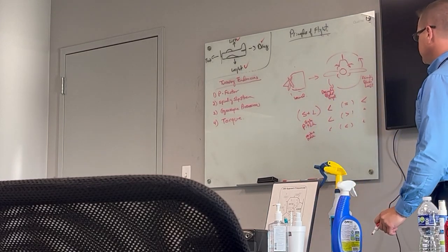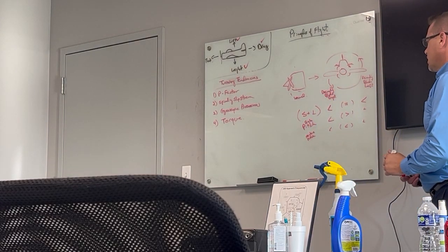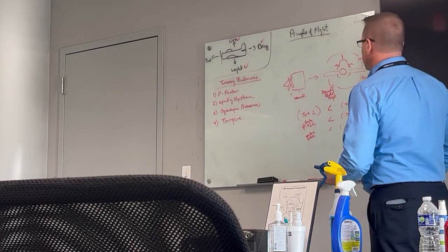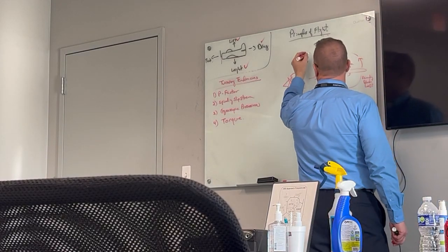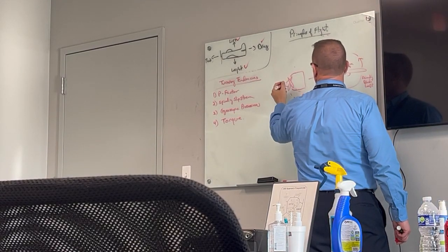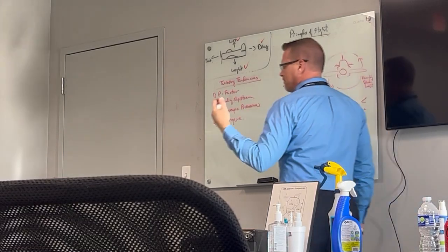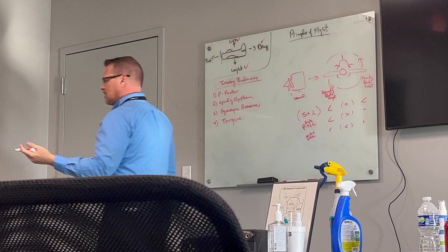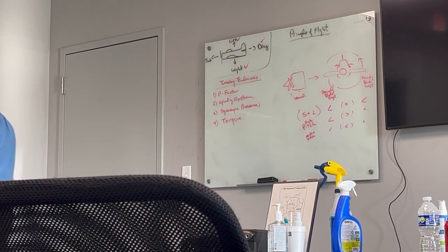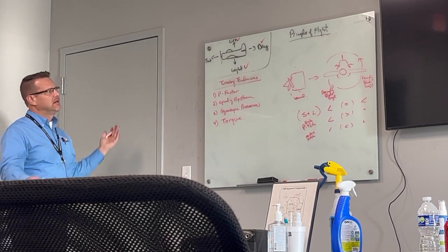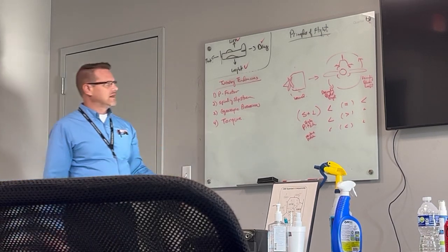So typically we talk about this in relatively high pitch attitudes. If we have a high pitch attitude, the descending blade becomes very flat, like a paddleboard, and the ascending blade becomes more like a knife and just slices through the air. It doesn't have a great angle of attack. One has a massive angle of attack, and the other has a very low angle of attack.